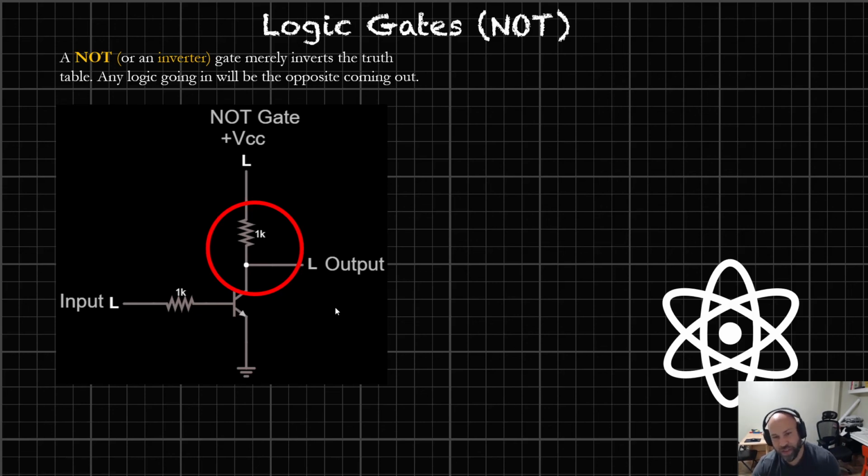It's really ingenious and unique because essentially by allowing the base to be energized, it's circumventing the output. So having the high here pulls the current down so that it doesn't go through the output and it forces it through the transistor instead. And that's how we invert our logic. If a line is high, energizing the base, then the current's getting drawn through the resistor, through the transistor, but not through the output, and therefore it inverts the logic.